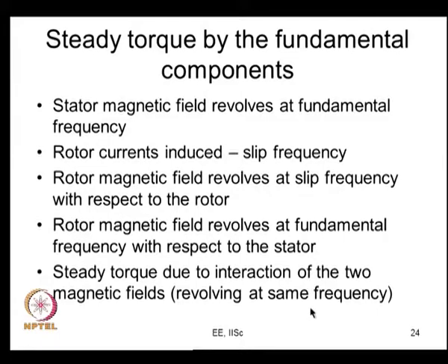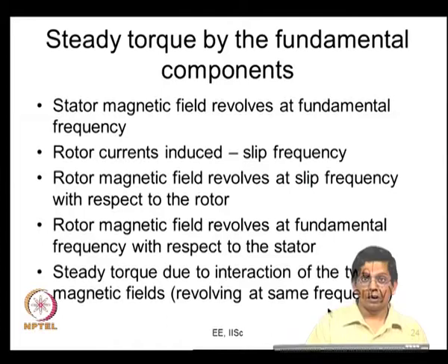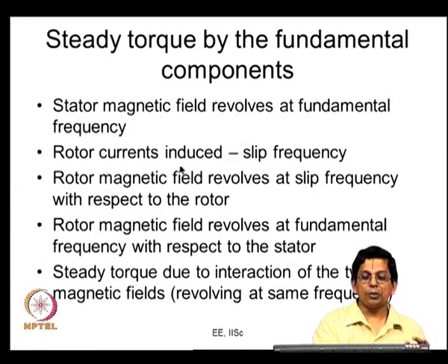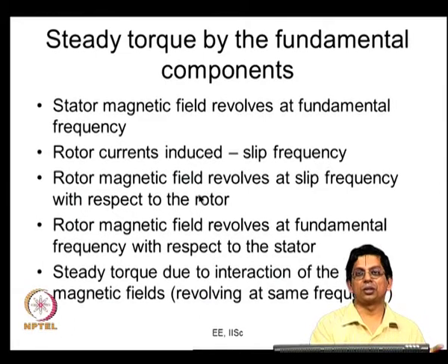So, both the stator and the rotor continue to produce the same thing, and the rotor goes on accelerating till when? Till it reaches a speed which is reasonably close to your fundamental frequency, that is what you call a slip. It will not reach the same speed as the synchronous speed. If it reaches the synchronous speed, then what happens? The slip is 0. When the slip is 0, the induced EMF in the rotor actually becomes 0, and there are no appreciable currents, and there is no appreciable torque.